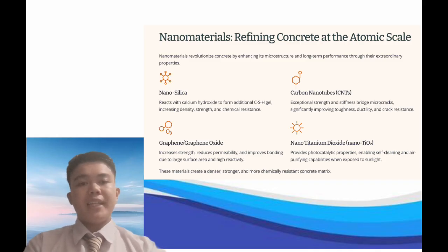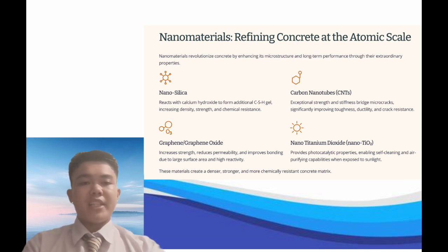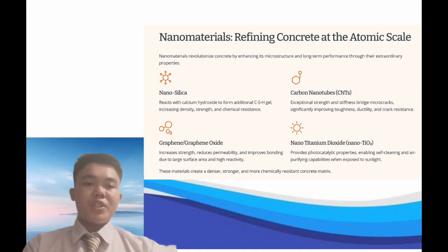During normal cement hydration, a significant amount of calcium hydroxide is produced. While not harmful, calcium hydroxide does not contribute much to strength and can even make concrete more vulnerable to chemical attack because it is relatively weak and easily dissolved by acidic or aggressive substances. Nanosilica improves this situation through a pozzolanic reaction.